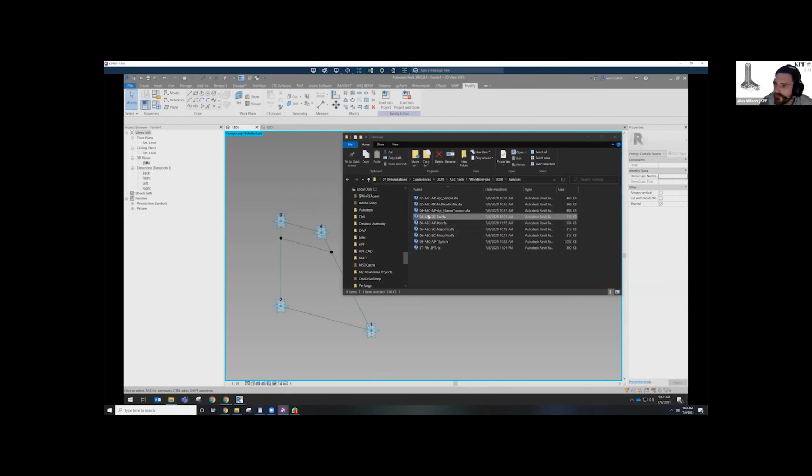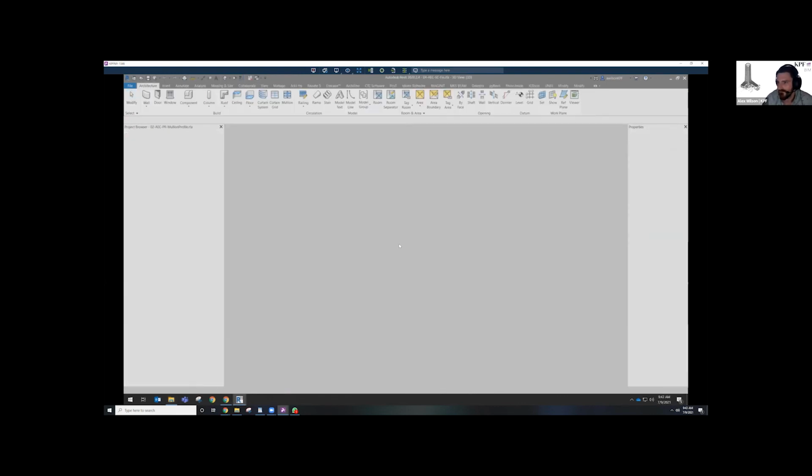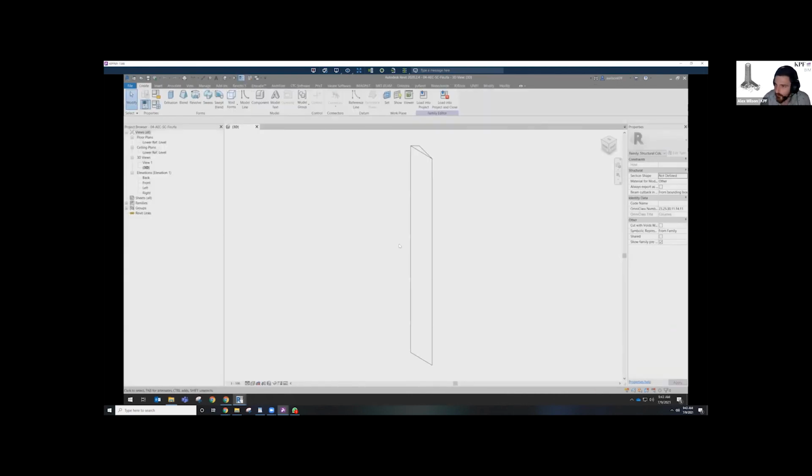The reason we did that is, one, for runtime. If you wanted to recalculate all of the fins and they were separate from the panels, it's super fast. If they're integrated into those panels, it went up to about 4 hours for creating the entire tower, which does not lend itself well to iterative design. By separating that out, you could run all of the fins in around 20 minutes and the panel stayed the same. This allows for ABA rhythms, attractor points, things like that.